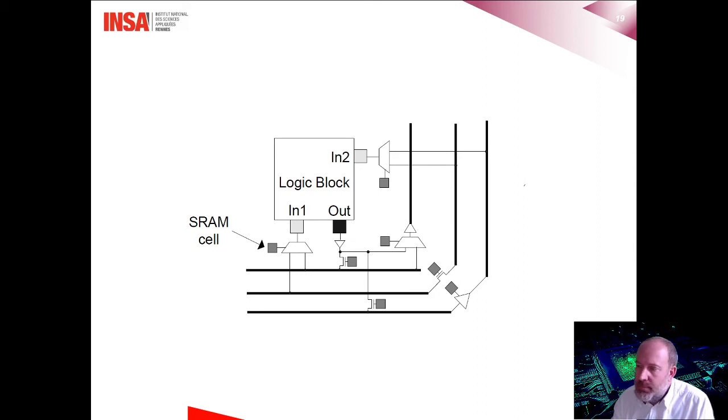In SRAM-type FPGAs, it's the content of the transistors between the row and the column that establishes the connection. Switching off the power erases the content of all transistors and therefore the interconnections between the cells. So switching the power off also erases the contents of the various logic cells. In this case, everything happens as if the circuit were blank.